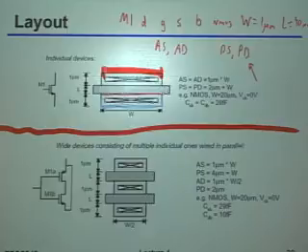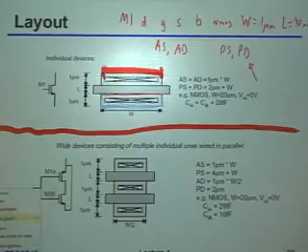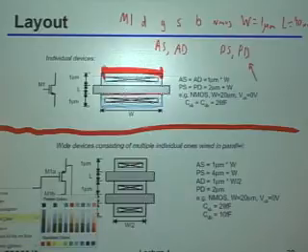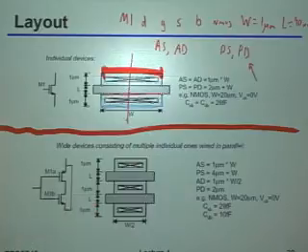So the geometric trick I'm going to play here, I'm going to initially just show conceptually how you would get there, and then the picture underneath it really shows what happens. So let's say I take this transistor that I'm building, and I split it into two pieces. Then I take, as an example, this left half of the transistor, and I just fold it over like this. So I literally just take that thing and essentially do this. If you think about it, that ends you up with the picture that I'm showing you here.